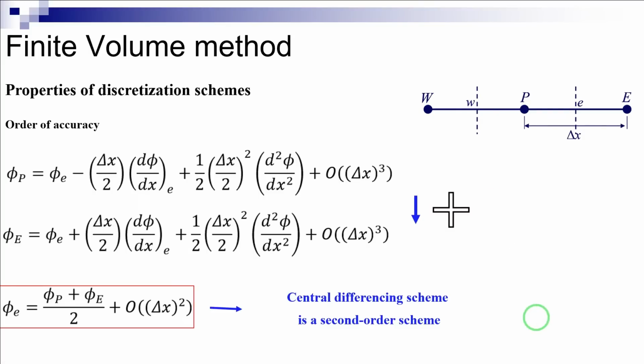If the order of truncation error in the discretization of the convective term is even, we are going to face a problem called dispersion, in which the solutions are going to have an oscillatory behavior. Schemes with lower order of accuracy, such as the Upwind scheme, produce considerable numerical diffusion in 2- and 3-dimensional calculations when the velocity vectors are not aligned with the grid lines. Economy. The economy is related to the time required to compute realistic flow problems using a specific scheme, which should not be prohibitively time-consuming.